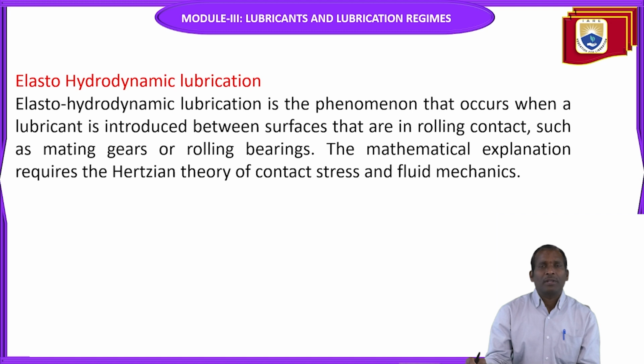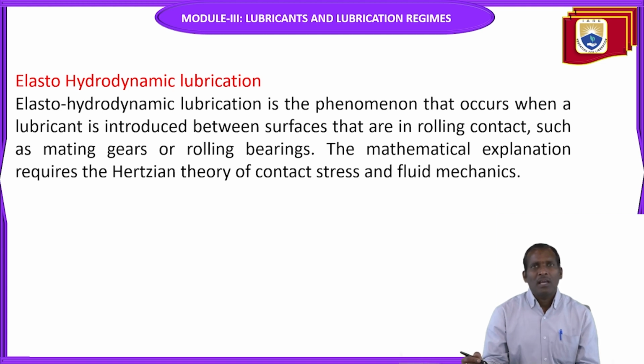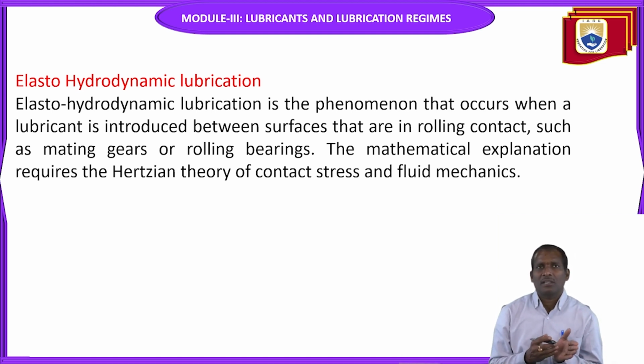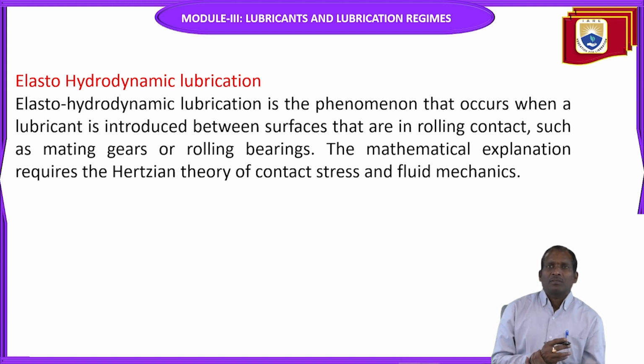Next one is elasto-hydrodynamic lubrication. Elasto-hydrodynamic lubrication is the phenomenon that occurs when a lubricant is introduced between surfaces that are in rolling contact, such as mating gears and rolling bearings. The mathematical explanation requires the Hertzian theory of contact stress and fluid mechanics.